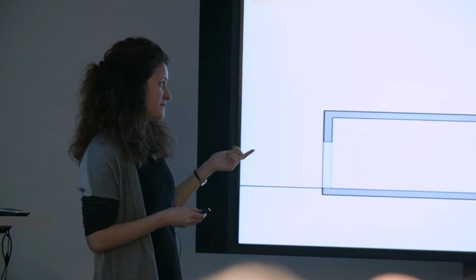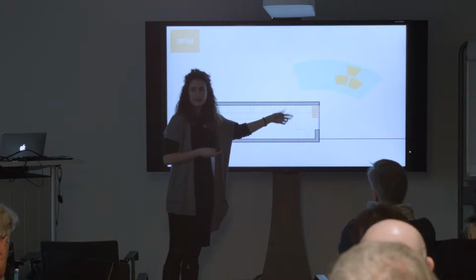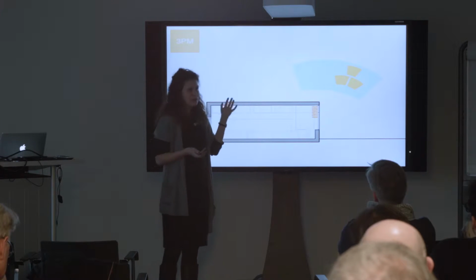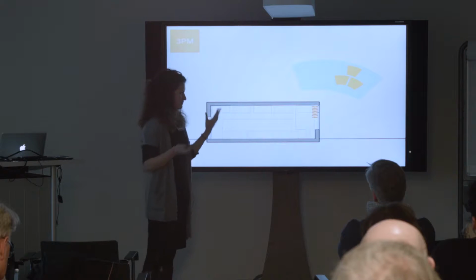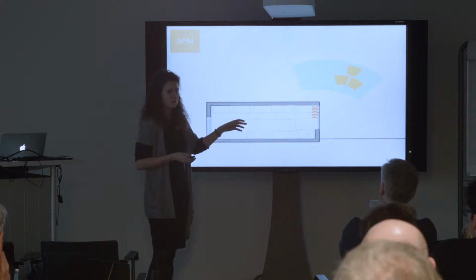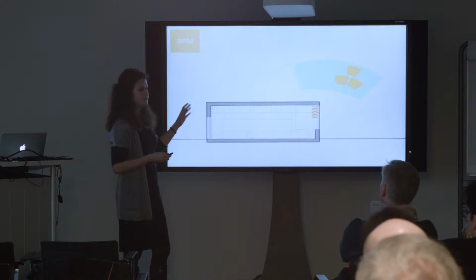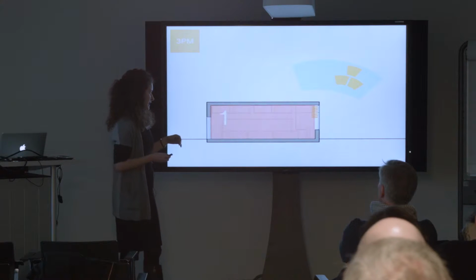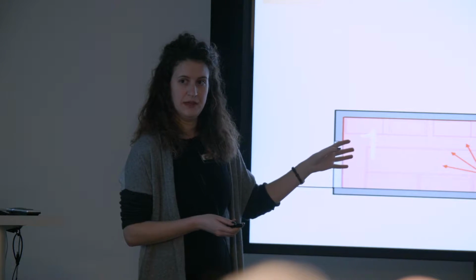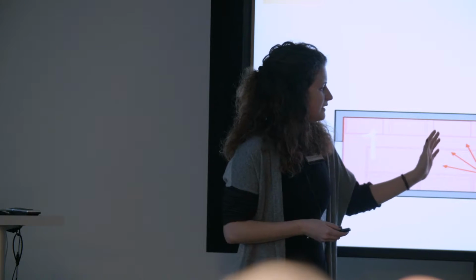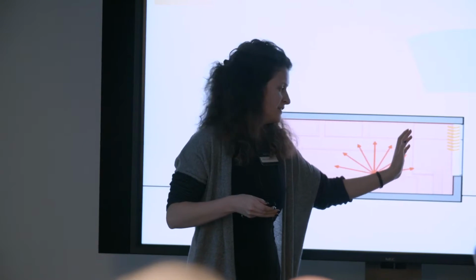After this, the 3-phase method came into the scene, mainly because there was a need to simulate complex fenestration systems, CFS. These are called complex, but can be as simple as a Venetian blind. Optically speaking, they're fairly complex to simulate and to represent accurately. So this process divides the whole thing into 3 steps, separate, as the name suggests. The first is sampling the interior part of our room with the rcontrib simulation run. With this sampling, we are looking at the window surface for the interior.